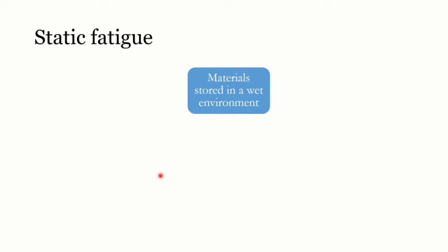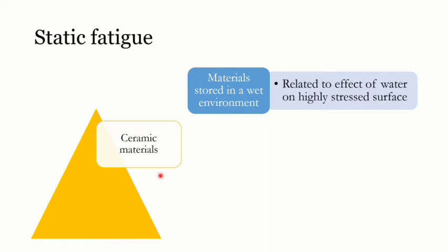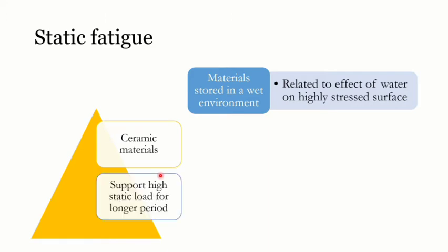So it is exhibited in some ceramic materials. What happens here is that when a material is stored in a wet environment, this will result in certain water effect. It is producing high stress on the surface. So this results in the failure of the structure here. This is what is called static fatigue.